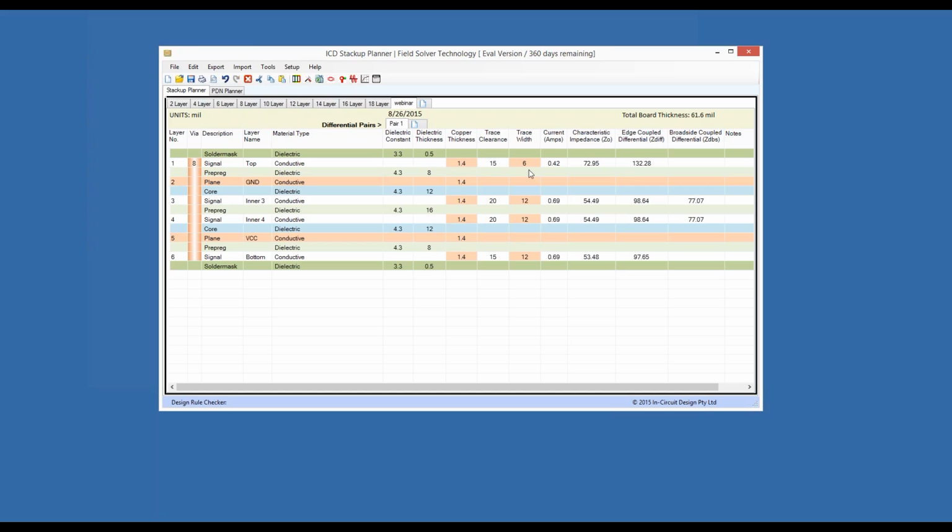So that's, again, why I want you to be very careful about the fact that in tools, especially like Altium, where you go into the rule set and you say, well, I got my stack up and I'm going to change a width because I just want to use this width, the manufacturer should be able to handle it. That's really dangerous because right now you've got a characteristic impedance for both single and differential pair that's way off. And if you did all the routing with six mils and you sent this off to the fabricator and they said, sorry, this isn't going to work, you're going to have to tear out that routing and you're going to have to do it based on these rules here.